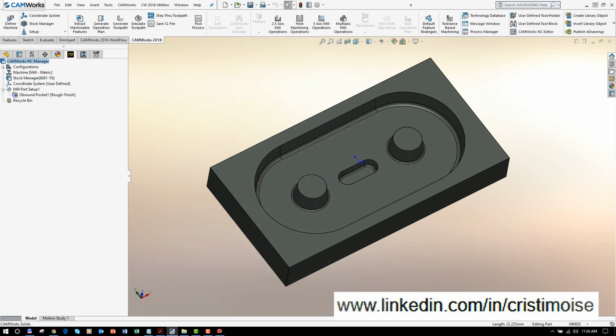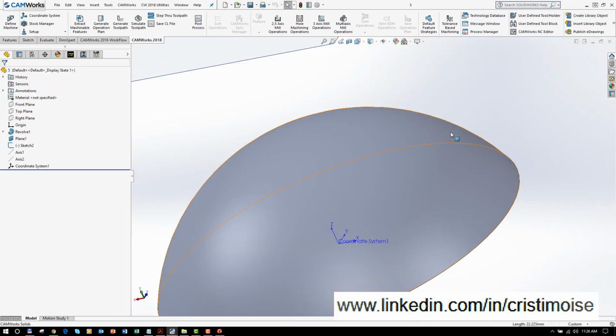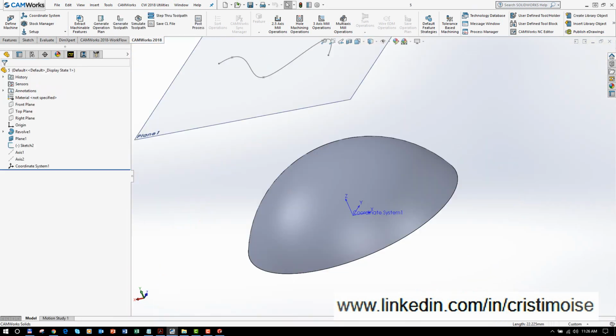Of course, another good enhancement is the multi-axis milling. What do we have in 5-axis? Well, I have an improved curve projection strategy, a very good enhancement for entry and retract, and side parameter, the extend and trim in the finish tab.